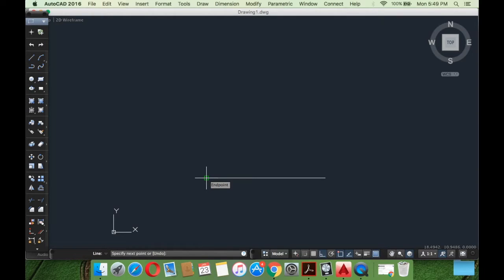We have already positioned the first point of the line. We type @, after that, sorry, I told you 50 as far as I remember, let's make it 20. Okay, @20 millimeters at an angle of 70 degrees.